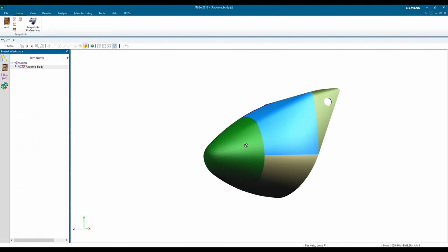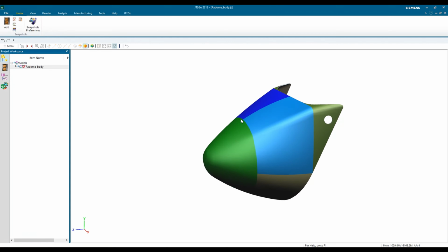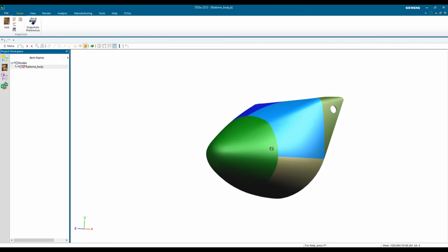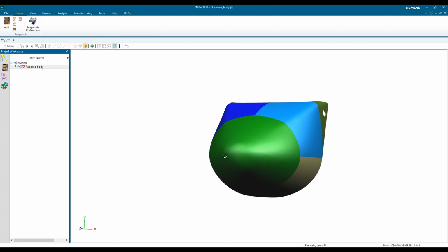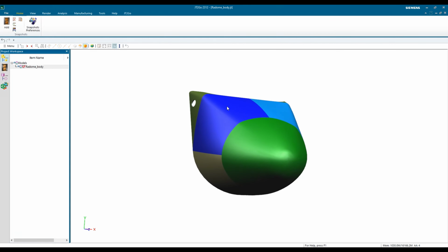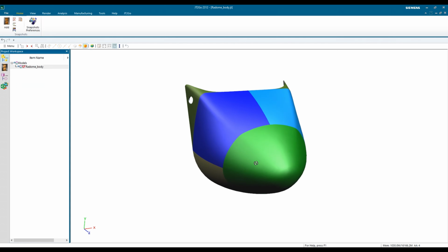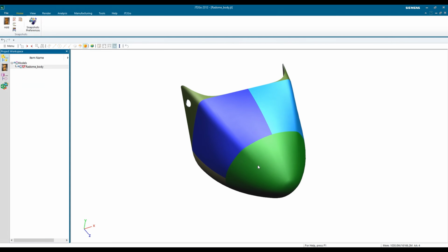And it is intended to be the nose section of a small airplane, either housing the weather radar, therefore we call it a radome, or it can also be housing any electronics. The front section should be as homogeneous as possible to enable the radar waves to pass through without any attenuation. And the remaining parts should be segmented into logical plies to enable easy and good molding during the manufacturing process.